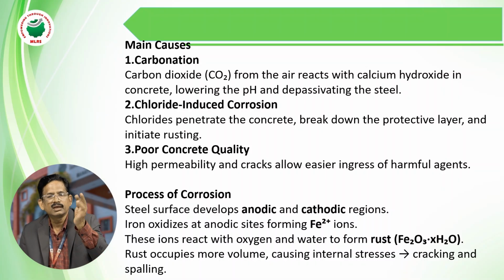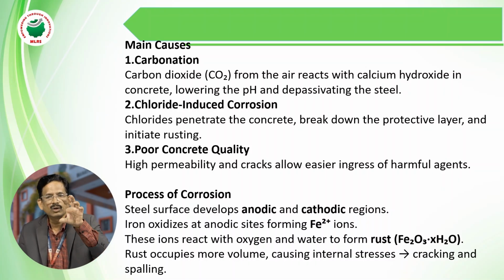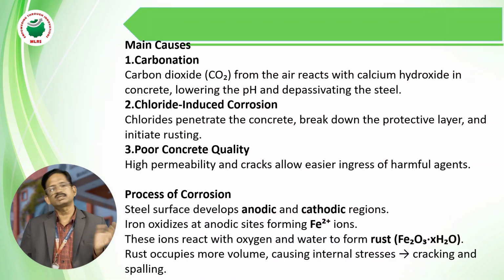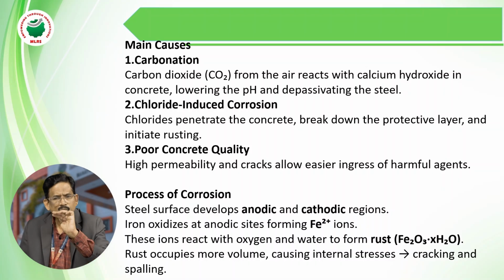So if we test a 1 foot length of any diameter, either 16 mm, 20 mm or 25 mm, you have to test it in the laboratory. First of all, we note down the load when the bar fails. Load by area will give the stress, and change in length by original length gives the strain. Stress by strain gives the Young's modulus of the steel. So for steel we test only the Young's modulus, or elongation also. So many tests are not performed for the steel, my dear students.